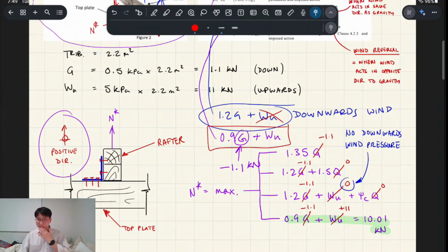The reason you don't consider 100% of the dead load as beneficial is because sometimes less stuff weighing down the system is installed in the worst case scenario. Say a 1 in 100 year wind event happens and just pushes the roof sheeting up, at the same time as all your dead load not being installed yet, then you're going to have this worst case scenario happen.